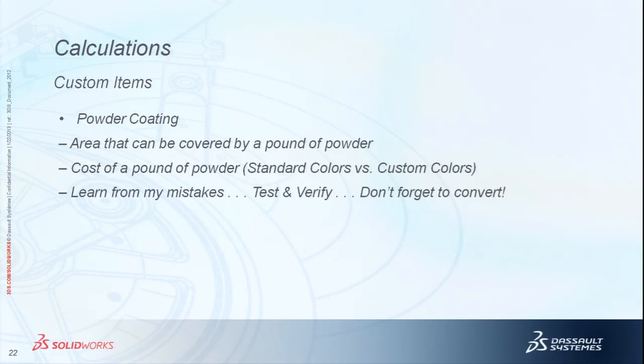Okay, test often when you're doing this, because this is where I really screwed up. I put in, 20 square feet, cost this much, boom, boom, boom, put it in. My first powder coated part was like $900 because it's looking for square inches. So just pay attention to the numbers. That's why I say to grab stuff off the shelf and know the numbers, because if it can break, I'll break it. PEM hardware, I got really lazy on this one.